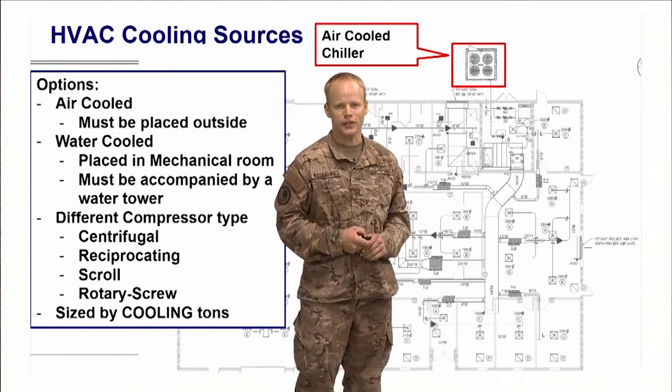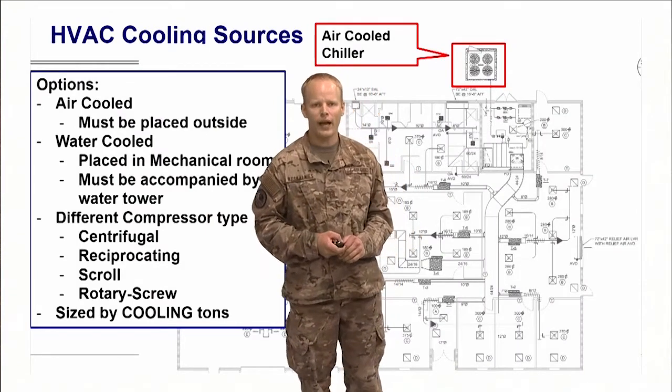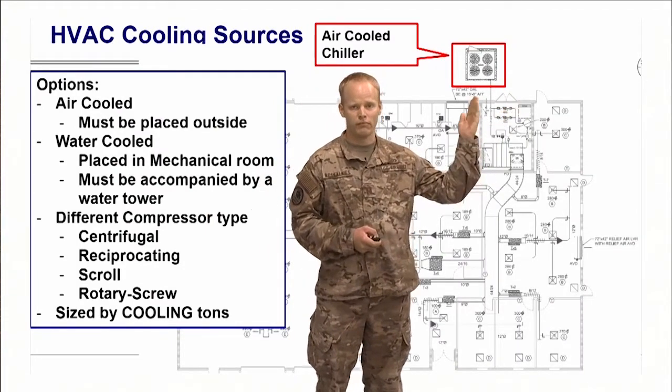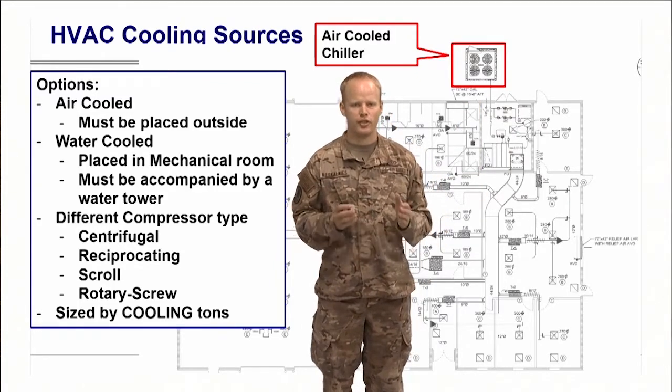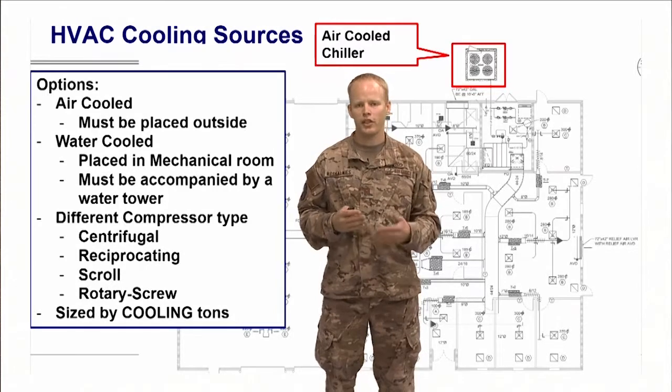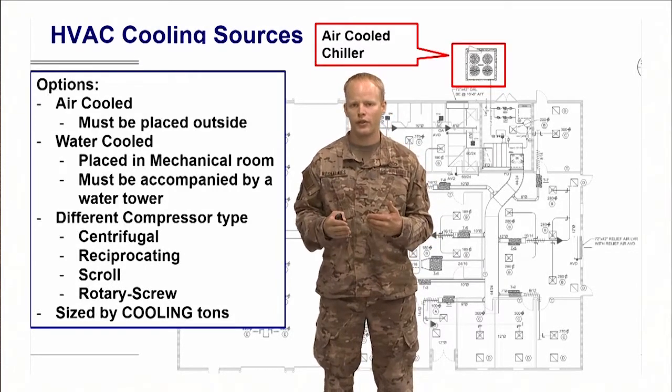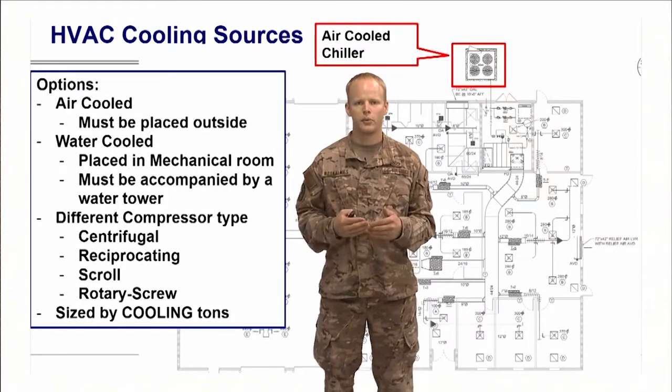So our cooling sources. I told you earlier, we have our air-cooled chiller up over here, which the purpose of the chiller is to create chilled water. Water is typically going to be between 35 degrees to 45 degrees to provide cooling.